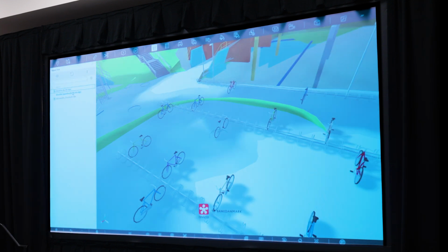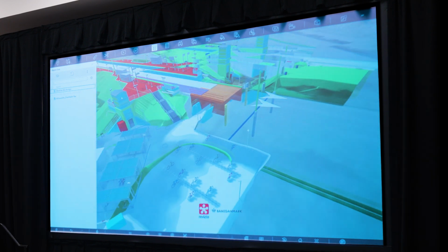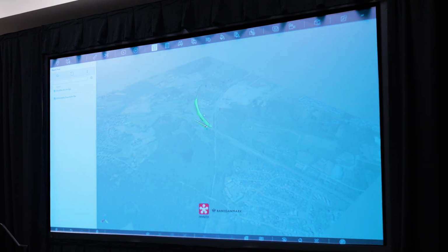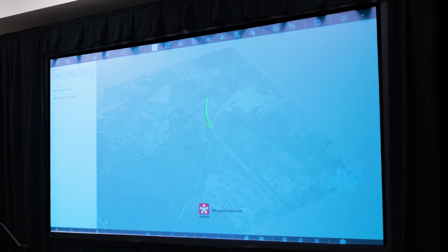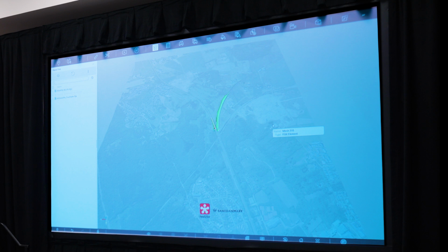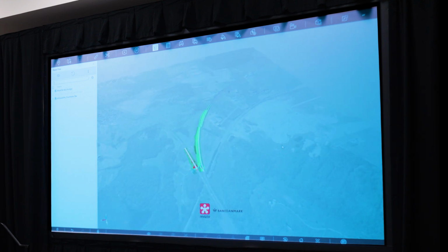This project is made up of Bentley tools, or information that's been authored in Bentley products. There's also an FBX file in here, so that's actually quite nice for infrastructure projects to bring in for context. It's quite a straightforward exercise to open InfraWorks, create a 3D model and export an FBX mesh file, and then you can bring that into Revizto. Yeah, and it's just a nice way to bring that information in.